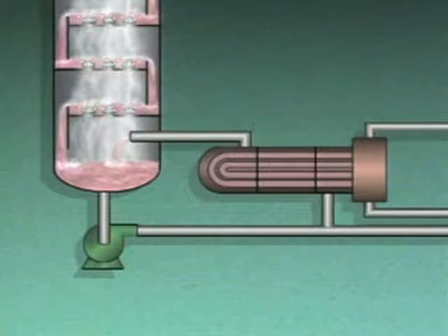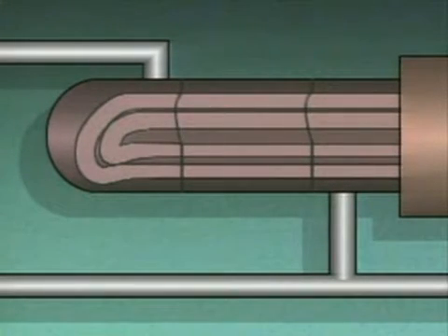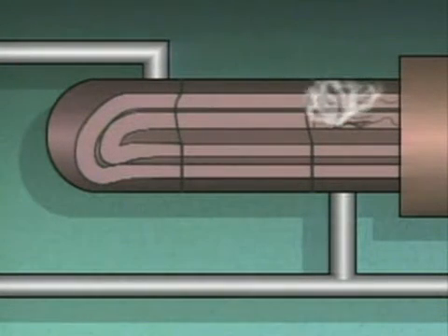Once the reboiler is ready to receive steam, the steam should be supplied gradually. If steam is supplied too quickly, the tubes in the reboiler could expand unevenly and possibly crack. If the column pressure is greater than the pressure in the steam system, some of the mixture could contaminate the steam system and damage it. If the column pressure is less than the pressure in the steam system, steam could leak out and contaminate the mixture flowing back to the column. Supplying steam to the reboiler too quickly can also cause the lighter component in the mixture to vaporize too rapidly. If that happens, the expanding vapor could rush up the column and possibly damage the internal structures of the column.